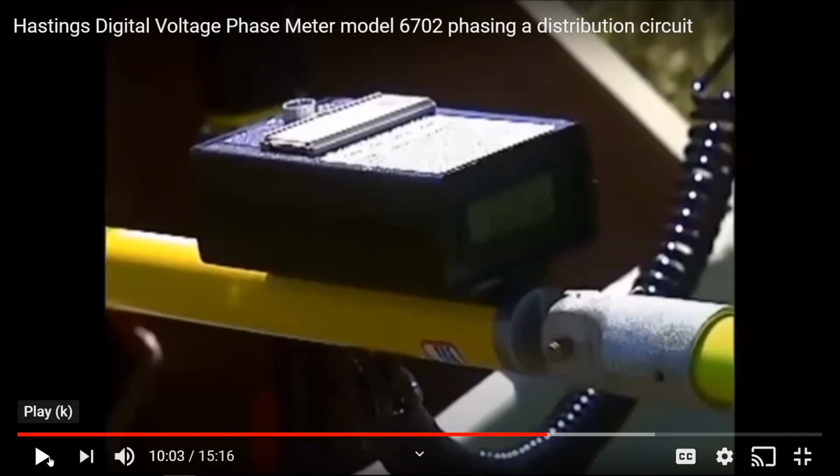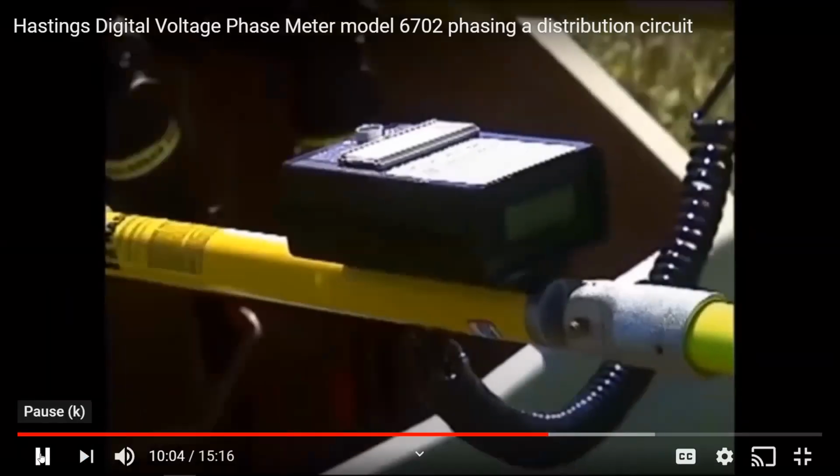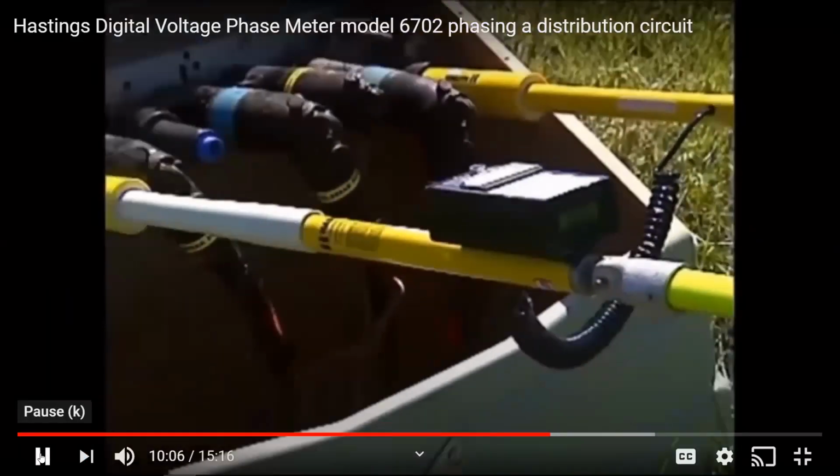Good cable. And what is happening there is you're actually just charging the cable up to 3,200 volts. And once it's fully charged, it has nowhere else to go. It's insulated. So we know we have a good cable there. Thus, the meter is going to read 0. Starts high, goes to 0, is a good conductor. No fault. Very good cable. It's held the capacitive charge.